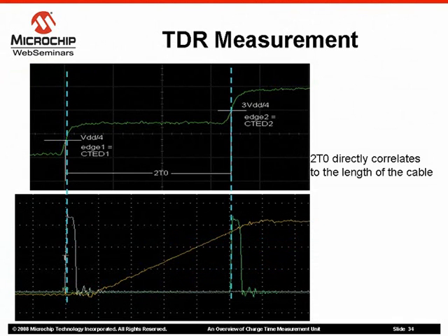The two-step waveform shown here is of an unterminated transmission line as shown in the scope plot here. The initial voltage at t equal to 0 nanosecond using equation at node A is 1 volt, which is nothing but Vp over 2. At time 2T0, the reflected pulse from the unterminated transmission line returns, and using the second equation, the voltage at node A is 2 volts, which is equal to Vp, which is the voltage of the pulse.